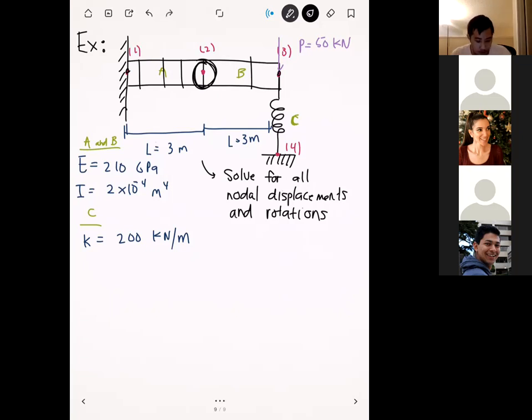But it's a good concept to talk about because you did a little bit of this in your first ANSYS activity, where I had you try the simulation with different numbers of mesh elements. I had you try one with a mesh of 5 millimeters. Then I had you increase that mesh size to 10 millimeters, and you saw the mesh get more coarse. And then I had you try one with 2.5 millimeters, which made the mesh really, really tiny.